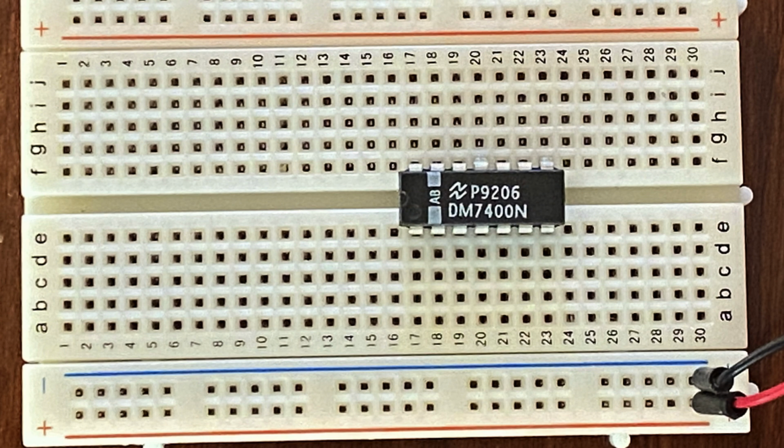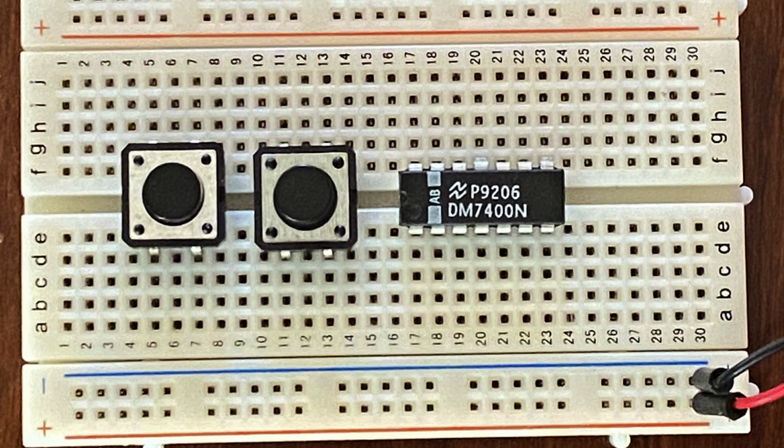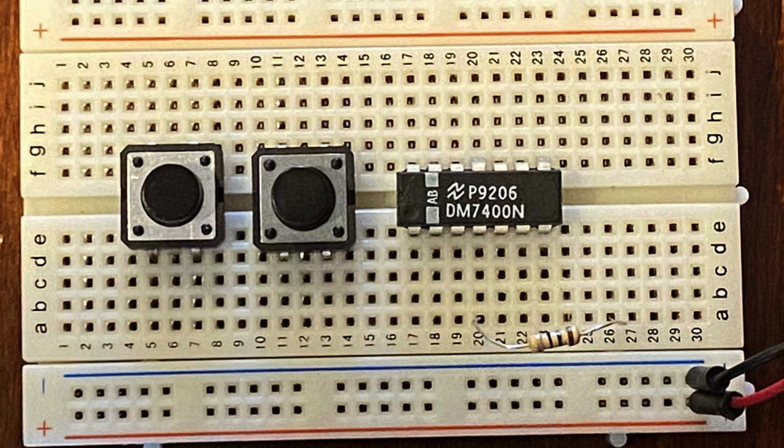We begin by placing the 7400 chip so that it straddles the center gap of the breadboard with 7 pins on each side of the gap. Also, we place the 2 switches so that they straddle the gap. We plug one end of a 1K ohm resistor so that it connects to pin 3 of the 7400. We plug the other end of the resistor into an unused column of the breadboard.